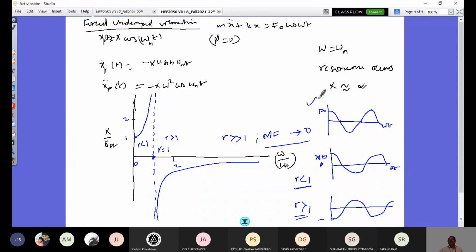But what is not preferred? Making these two meet is not preferred. If these two are meeting, then you'll have an amplitude that rises to infinity, leading to breakage and non-functioning of your system. Why? Because there is no measure of damping. This is not a damped system. That's one. Mathematically, what's happening, understanding this is needed. But any time, your system will have sufficient damping so that this peak amplitude does not reach infinity, rather it would be at a finite value, where the material property would take care that it falls below the yield point of your system, and so on. That's the fundamental of design.